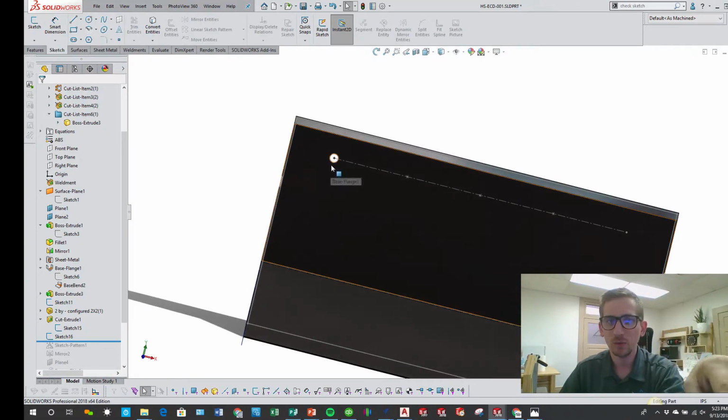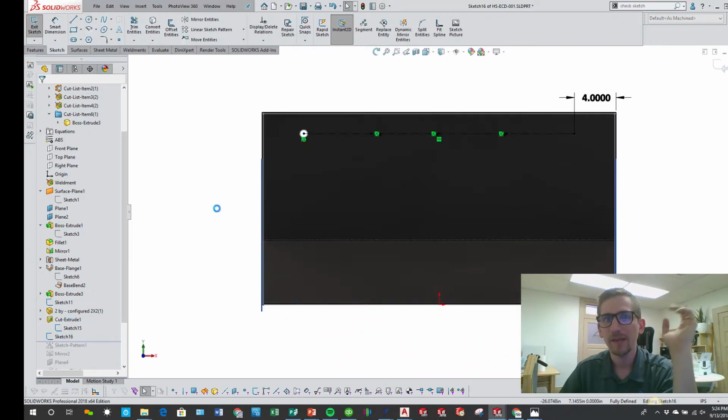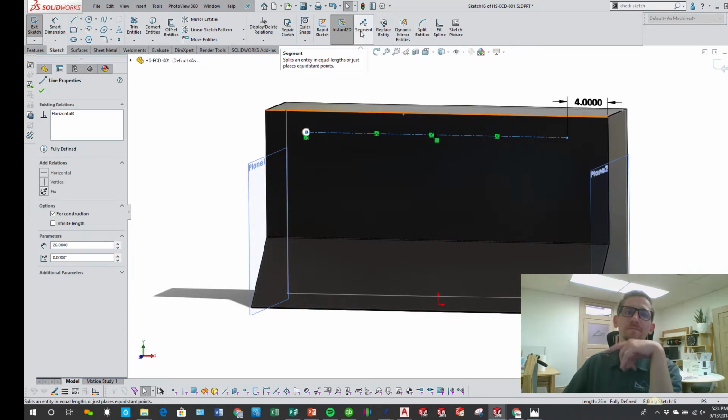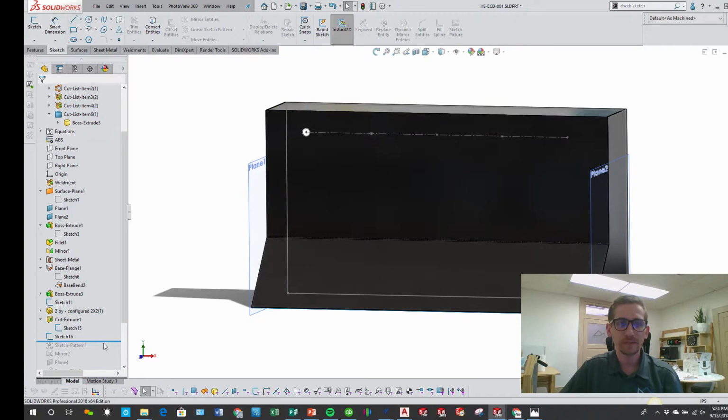And so I got this hole here. And then I did a new sketch, and this sketch is utilizing a tool called Segment. And what Segment does is, if you have a line here, I know it's a little hard to see, but that line, I simply select it and select the Segment tool, and I specified I want to have 3 dots on here. And what's so cool about this is after I do that, I could come in and do what's known as a sketch-driven pattern.